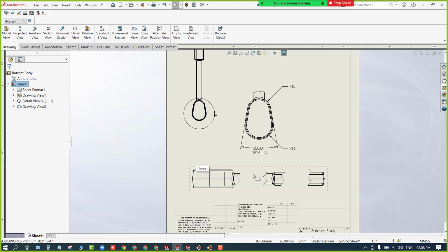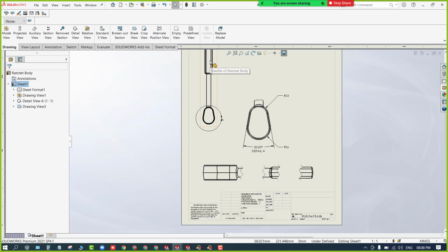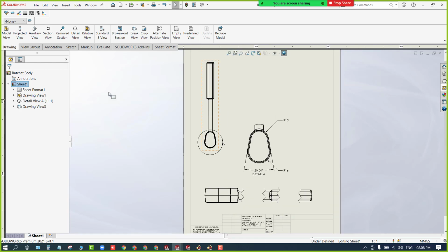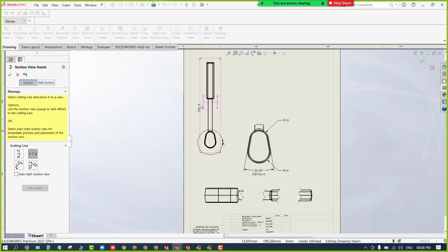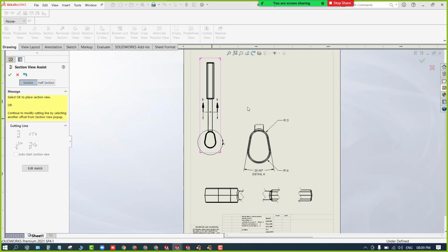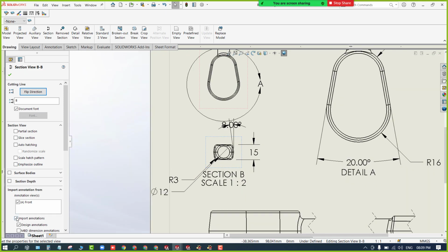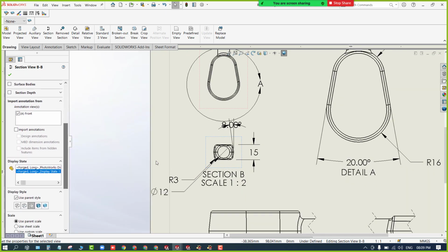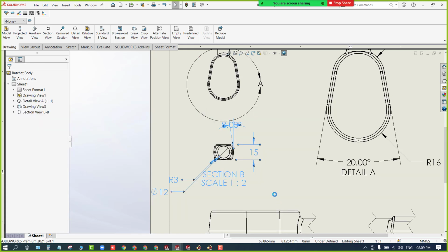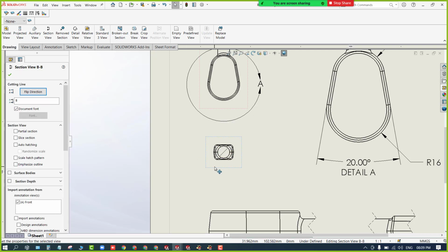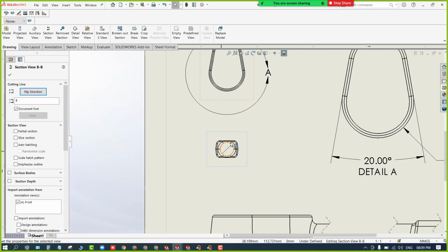Now here the circular section is there, no? I need to place it, and here the cutout of this is kind of hexagon. So we'll do the same now. I need the section views of it. You can go to section view, select the view, and use the different options over there, but I don't want all the dimensions to be added. You can uncheck these options, we can remove them, delete. Okay, in this drawing I want only the section, not everything.